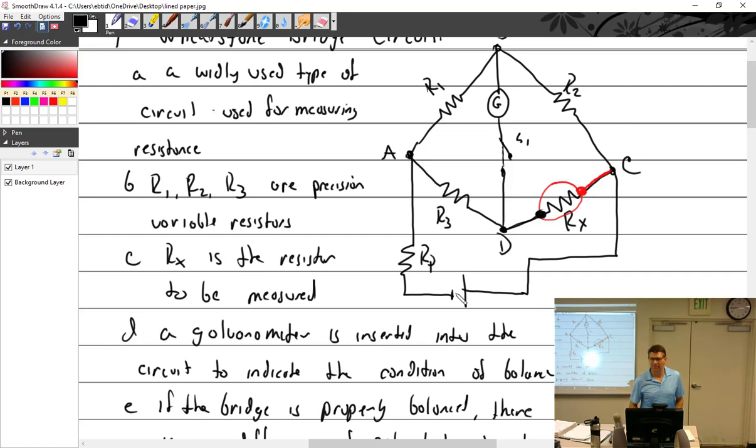Is this what's in the Simpson meter? Yeah. What is it that we're trimming when we're seeing this? I think it's this right here. Not 100% on that, but I'm pretty sure it's that, because that's the unknown here. Or it could be you're balancing out one of these, but I don't think so, because these are precision. You're balancing out this little bridge circuit so that you get no flow through the meter.